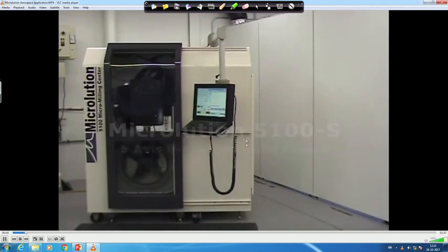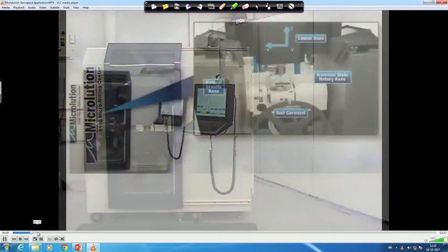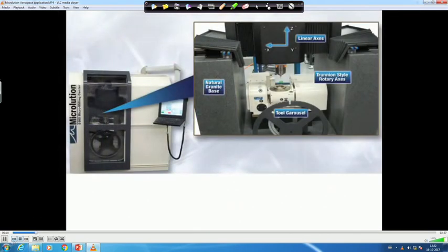So, this is the 5 axis machining center. Now, see what things you need in this case, and how these machines are different compared to the conventional CNC machine. The base material is granite, because mostly we use cast iron or some other material with a high damping coefficient, but here the damping efficiency is very high.